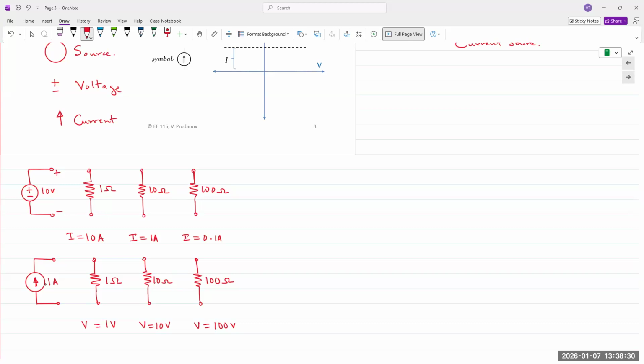So also the resistor itself that we are using would not be able to withstand that much energy. Right? Electrical energy power is a product of voltage and current. So 1000 volts, meaning 1000 times 1 gives us a million watts. Resistors are like quarter watt resistors. So there is a current limit and a voltage limit that is set on every power supply.